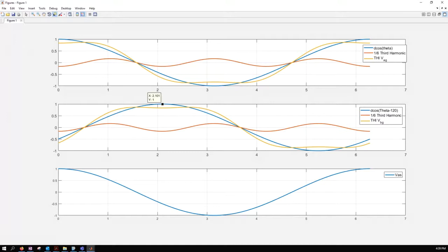so what, right? So why do we care? So the interesting part is when you look at the phase to phase voltage, when you look at VAS, which, if you recall, we used the inverter voltages VAG, VBG, VCG, and we computed VAS based on a combination of those, right? Even though VAG, VBG, and even VCG, are going to have this third harmonic injected component.